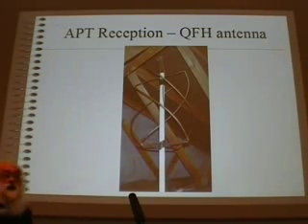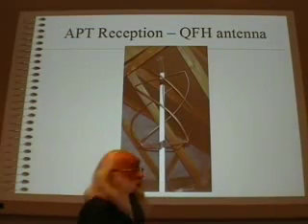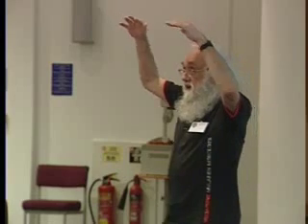You've seen the turnstile antenna outside that Francis Bell has showed. This is a very popular antenna, QFH antenna. It actually matches the ones that they actually have on the satellite for broadcasting. It has a nice radiation pattern, so it's overhead. It's relatively low gain. Towards the horizon, there's an increasing gain, and that tends to nicely compensate for the path length losses.